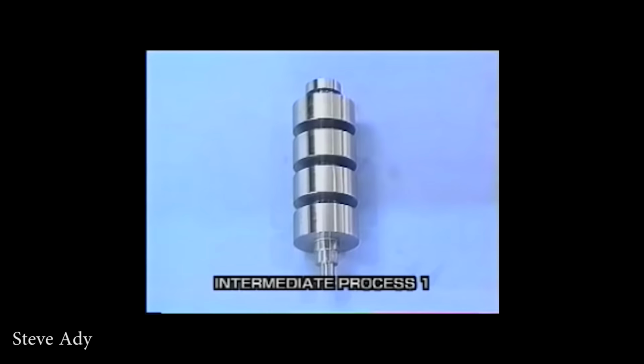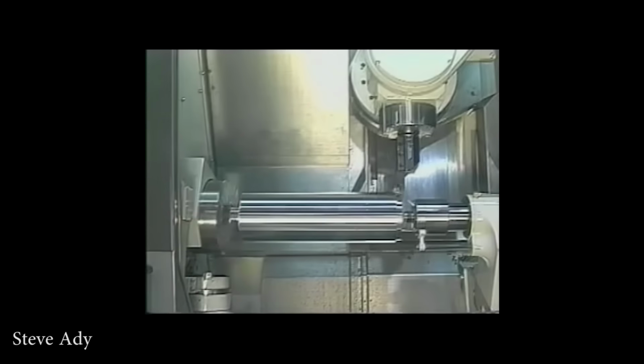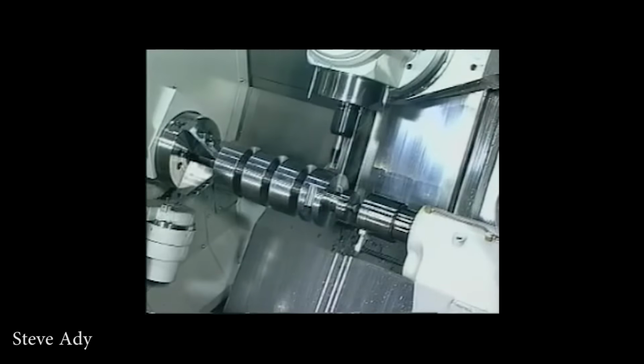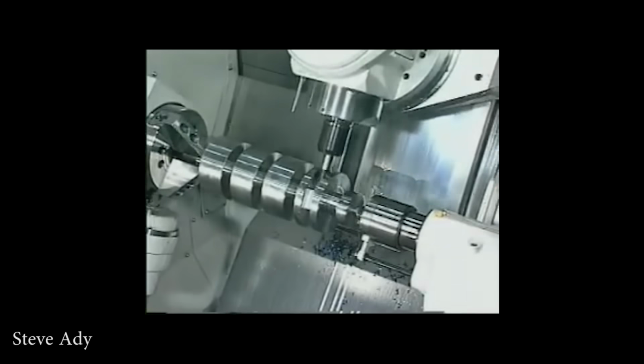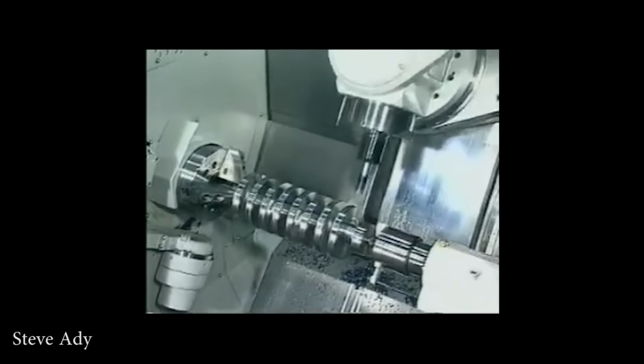When it comes to billet crankshafts, there's no forging or casting. You simply take a billet and you machine away until you're left with a crankshaft. Naturally, this process takes a long time and a lot of material gets removed. And this is why billet crankshafts are usually pretty expensive and often reserved for racing and other extreme applications.